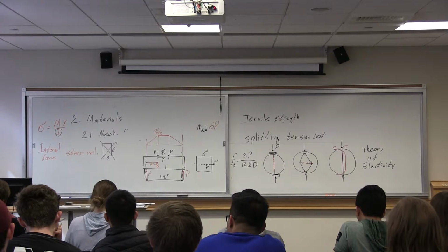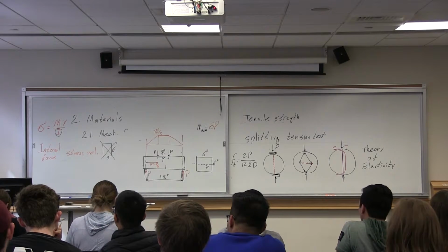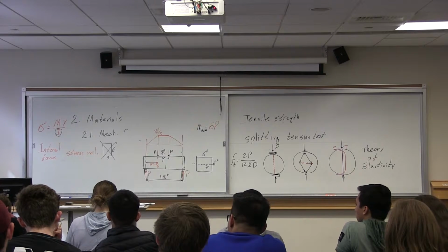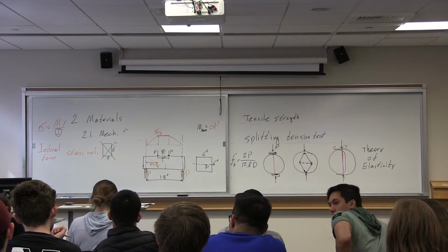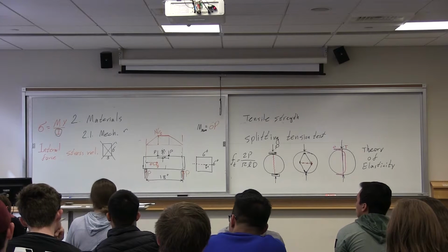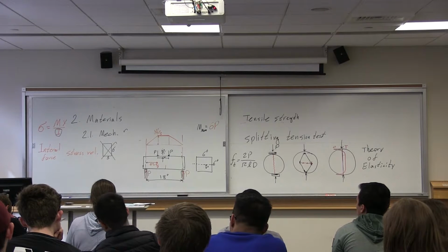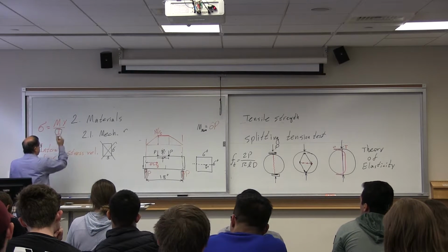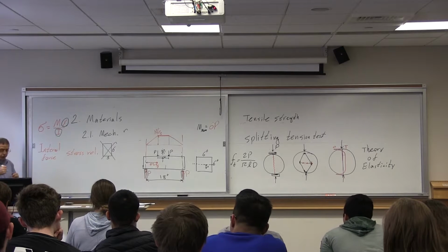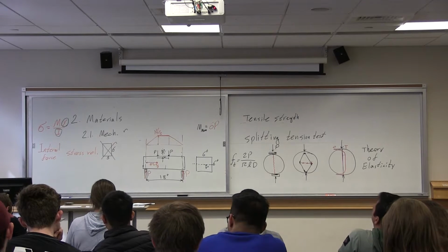Geometry. They have nothing to do with material properties. If you make this beam out of concrete, steel, wood, or whatever, y and I don't change. So that's also important to recognize. These two are geometric characteristics.